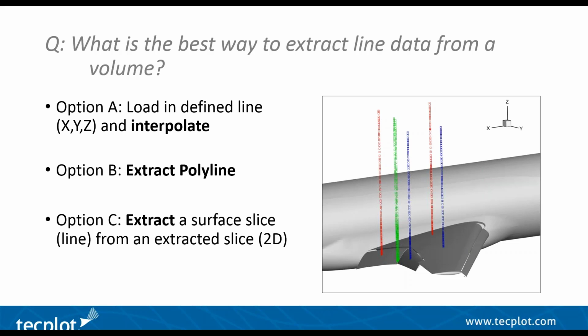But since we're going for the same extraction from model to model, this is constant, or it should be fairly constant. Although we did have to define a specific location very close to the surface, and then use blanking, because the wing changes in the z direction throughout, so we didn't want to lose any of the boundaries there. Okay, so you just blank just inside the surface a little bit, and then you blank at an arbitrary extension. Excellent.